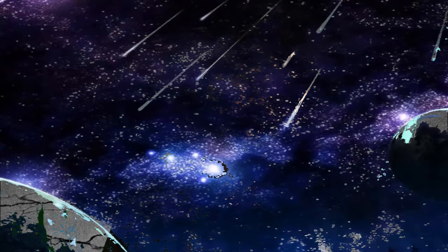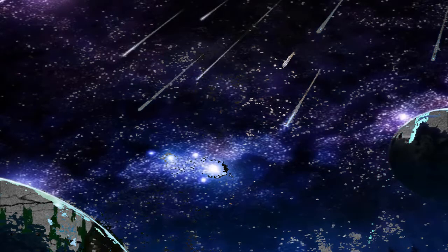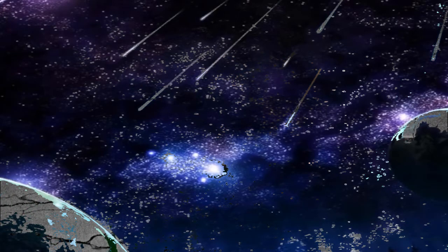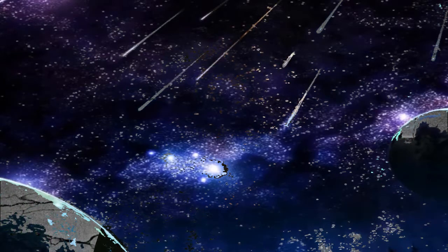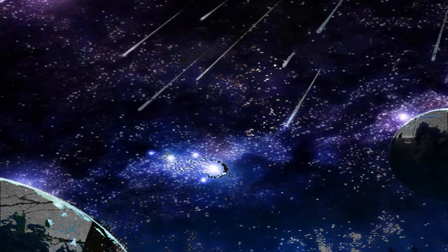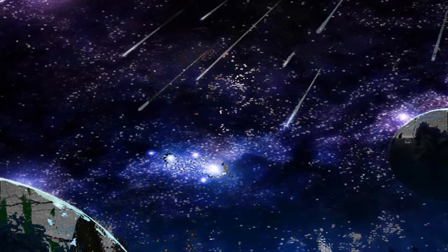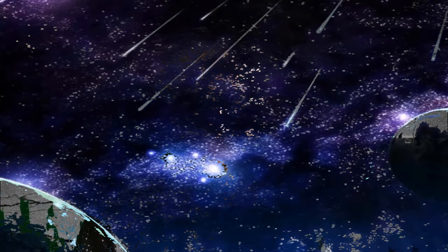Now, each of them has a different weight and they will settle at different terminal velocities. So the liquid droplets settle at different terminal velocities. Then smaller droplets coalesce and they form bigger droplets. So that is one of the principles we're going to be looking at in terms of separation.